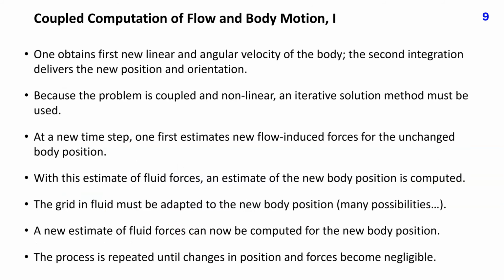As shown in the preceding slide, one obtains first the new linear and angular velocity of the body. The second integration delivers the new position and orientation. Because the problem is coupled and nonlinear, an iterative solution method must be used. At the new time step, one first estimates the new flow-induced forces for the unchanged body position. With this estimate of fluid forces, an estimate of the new body position is computed.